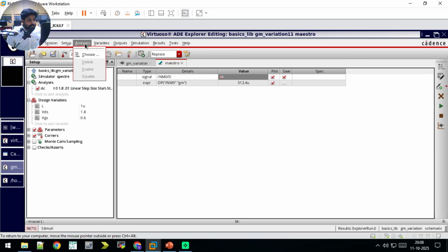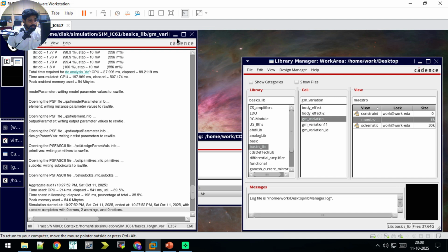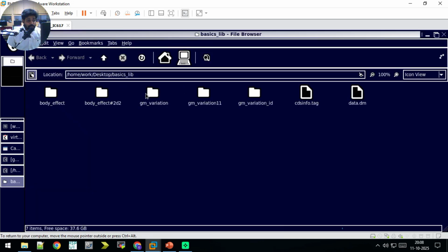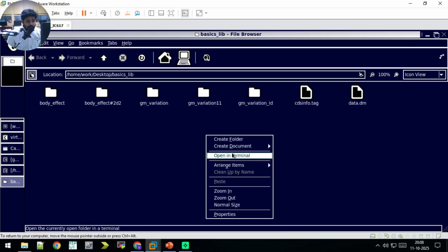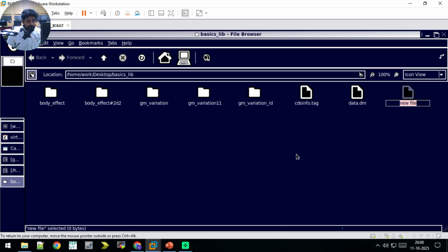So what we do is we'll be going with operating points, we'll save it over here in the folder where I'm doing the project. This is the drive location where I have to create an empty file with whatever name you prefer, that's your wish, but with the extension SCS, Spectre circuit simulation file. I'm saving my operating OP. Yes, this is the name that I'm preferring for this empty file.